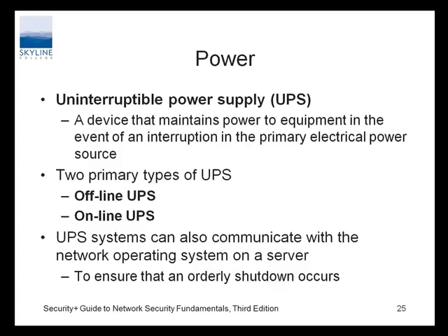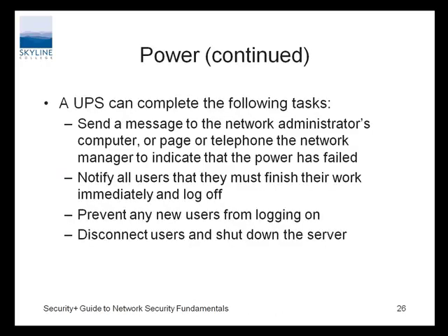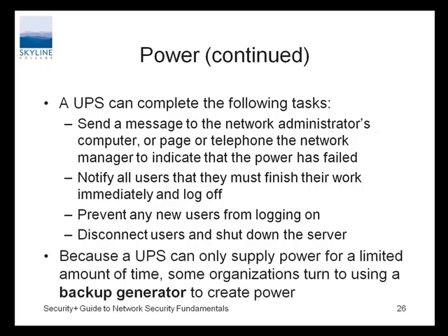Oh yeah, and they can communicate with the server, should communicate with the server, so if the power goes off, these things are not intended to stay on for hours at a time. They're designed to stay on for minutes at a time to do an orderly shutdown of the server. And they can actually be programmed to start that shutdown process: notify users to save their work and get offline because we're about to go down, prevent new users from logging on, disconnect the users, and shut down the server. That's what we should have these things set up to do so that we preserve the data.